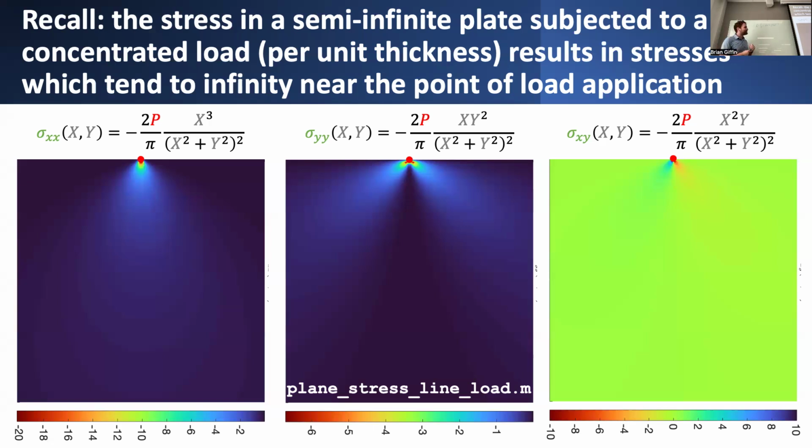Really, this assumption only becomes invalid when we have solutions where the deformation of this body might include very large rotations or very large amounts of stretching. And certainly if you have a very high stress in this local vicinity, then maybe you do have some relatively large deformations there, but it doesn't necessarily explain why the stresses would go off to infinity.